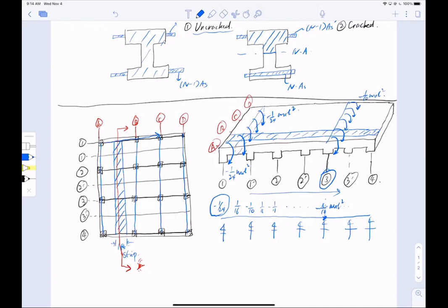Now, yes, A, B, C, D are here. So along this direction, you have A, B, C, D. Sorry, you have 3 spans, 1, 2, 3, something like that. 1 bar, 2 bar, 3 bar, to differentiate. So you have 3 spans, but these 3 spans have nothing to do with the moment coefficient this way. In other words, when you're trying to evaluate whether you can use moment coefficient or not, you are going to use geometries only along the 1, 2, 3, 4 span direction.